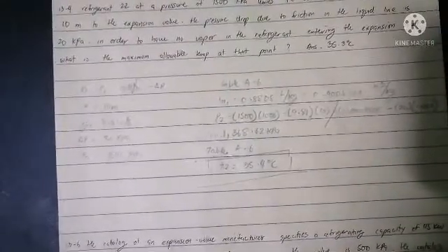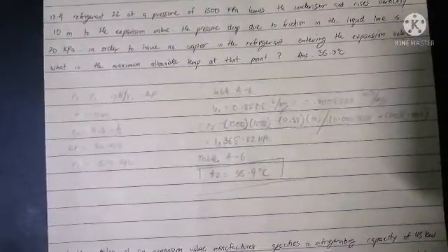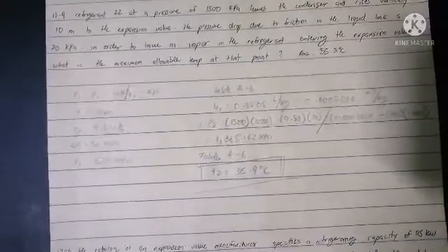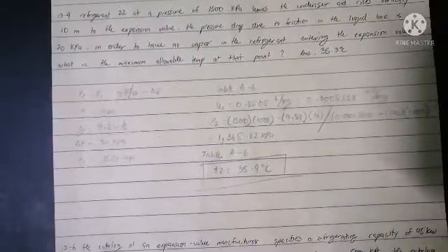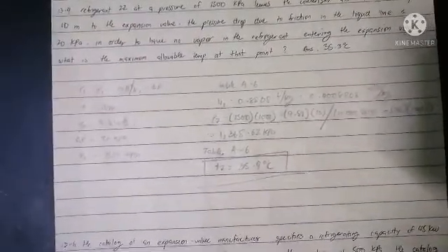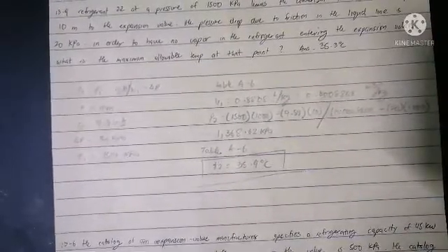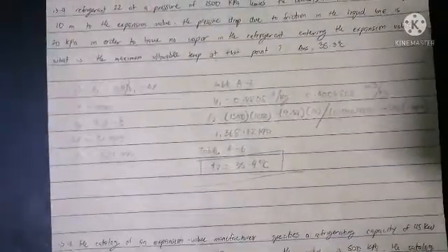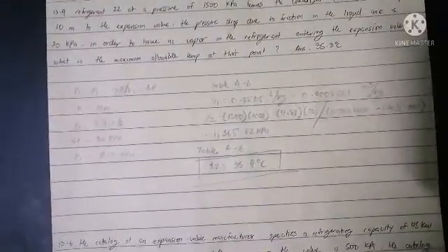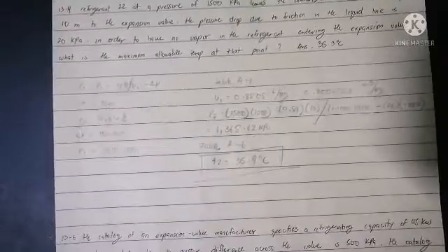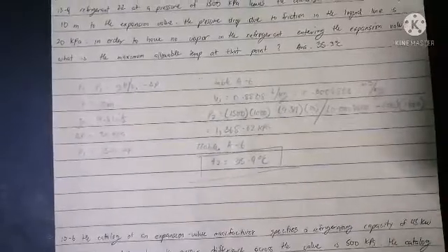and P1 is 1500 kilopascal. So from Table A6, v equals 0.8808 liters per kilogram or 0.0008808 cubic meters per kilogram. So our P2 equals 1500 times 1000 minus 9.81 times 10 over 0.0008808 minus 20 times 1000. So that is 1368.62 kilopascal. So from Table A6, our T2 is equal to 35.4 degrees Celsius.